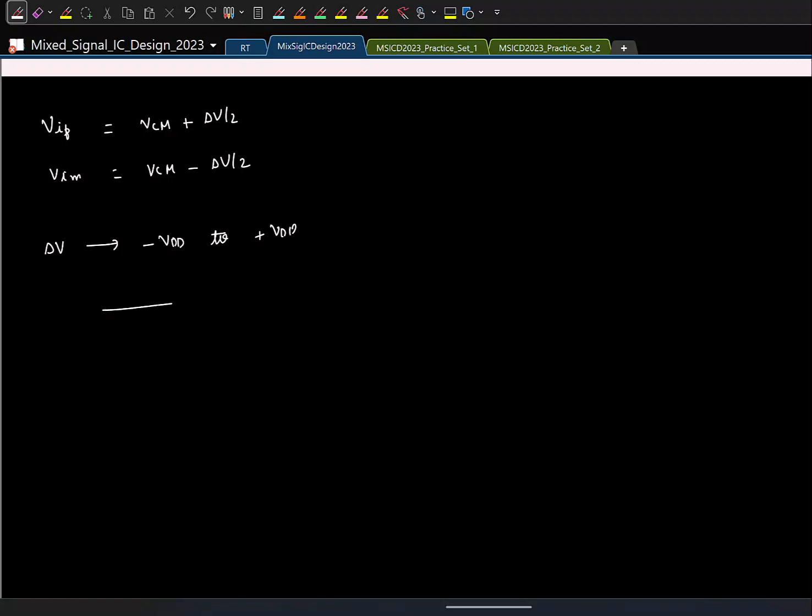So we basically have to cover this range, compare a differential input with a whole bunch of reference voltages here, and these are the differential references, say some Vref,k, and make the decision. And being a differential circuit, even the references we have to supply in a differential manner. So let's say this is the plus reference for the kth reference. This is the minus reference voltage for the kth reference. So Vref,k is the differential reference. How do we give the individual references?